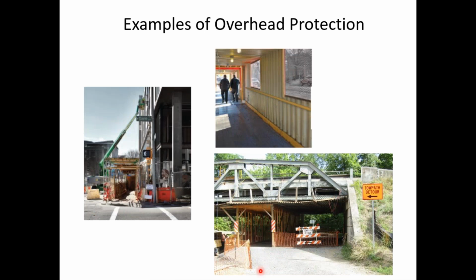My only concern with this is not so much the canopy itself, which looks fine, but notice the entrance to the canopy from the trail. This area here, there's a type 3 barricade again, it's not detectable. There's that maybe snow fencing. I think Lisa raised that question. In my mind, this arrangement is not detectable.